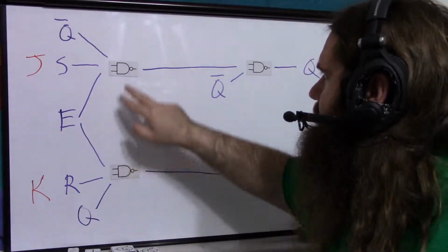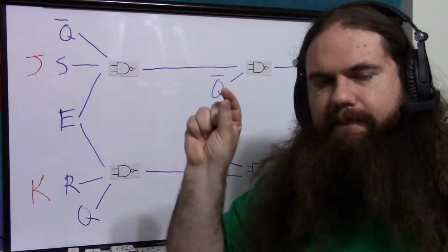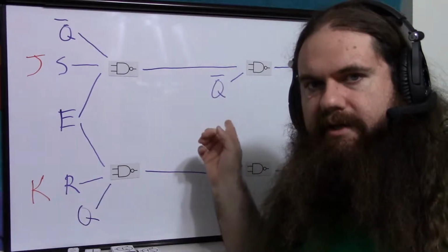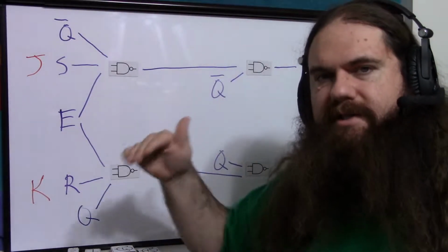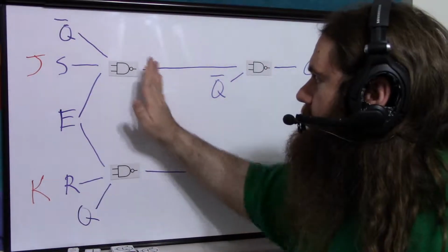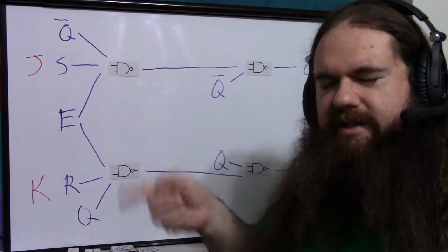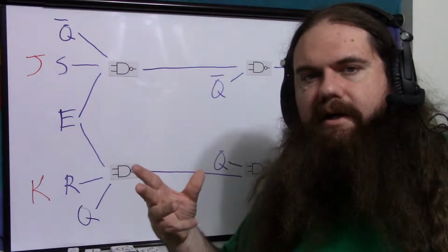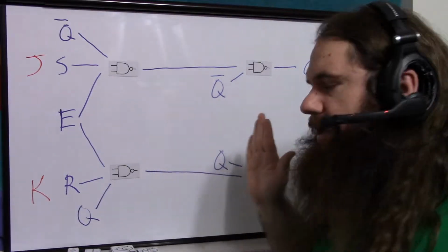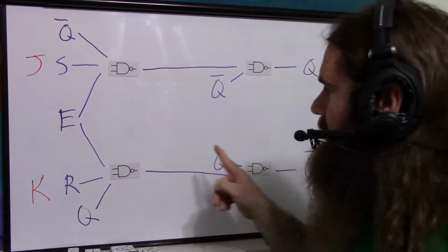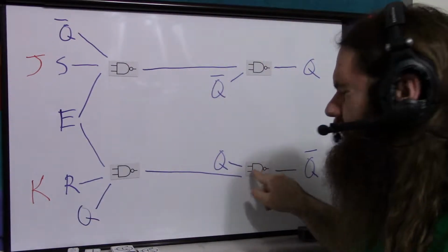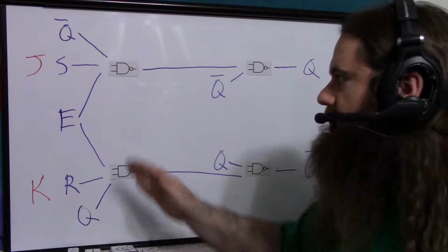Remember, each of these symbols is an independently powered set of transistors. So once you have gotten one of these feedback transistors to send out the feedback signal that's going to get the other transistor to do its thing, then you don't need to do the inputs anymore. It's sustaining itself until the next time you override the feedback. So you turn on your clock just long enough to kick the feedback into changing, but that doesn't change Q yet. It just causes the transistors to begin to move, and then you stop it again.